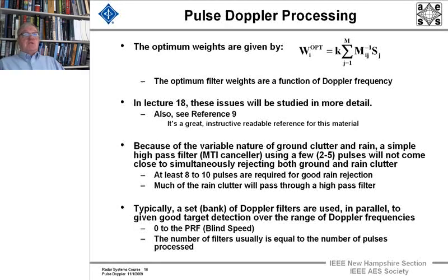That Fourier transform is the autocorrelation function of that clutter with its spread. And you sample that autocorrelation function at your sample between pulses. And that is this covariance matrix that you have to take the inverse of.